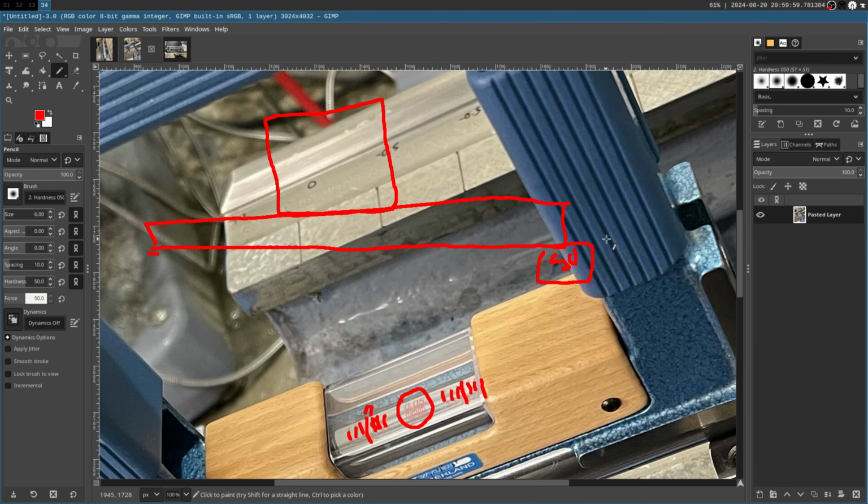You take the level, you set it down, and then you rotate it 180 degrees, and you set it exactly down on the same footing it had, and you want it to read the exact same reading. If it reads the same reading, then that means that everything in the stack up is level and parallel and adjusted, right? And that's the really cool thing about levels.